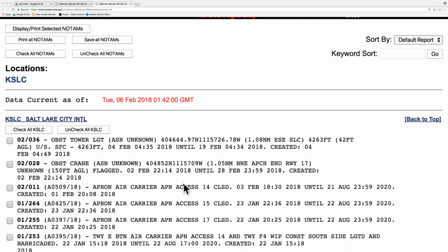What does a D NOTAM specifically tell us about? It's information on the status of your navigational equipment. More than that, though. Runways, taxiways, radios, your physical equipment at the airport. So a D NOTAM, the D is related to local. A D NOTAM is a local NOTAM, is what they call them.